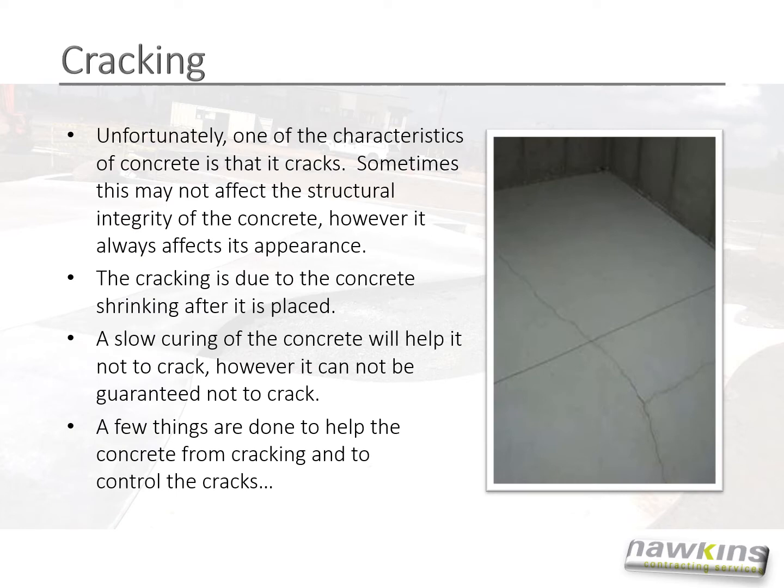Cracking. Unfortunately, one of the characteristics of concrete is that it cracks. Sometimes this may not affect the structural integrity of the concrete, however, it always affects its appearance. The cracking is due to the concrete shrinking after it has been placed. A slow curing of the concrete will help it not to crack, however, it cannot be guaranteed not to crack. A few things are done to help the concrete from cracking and to control the cracks.